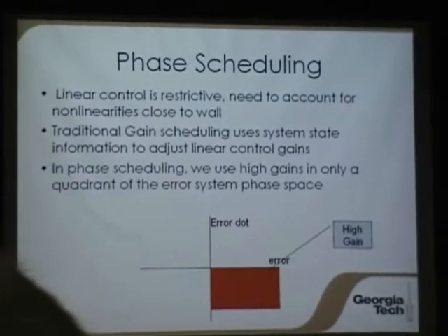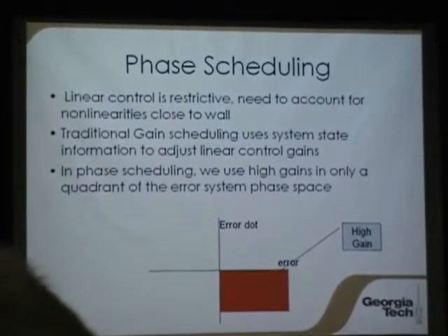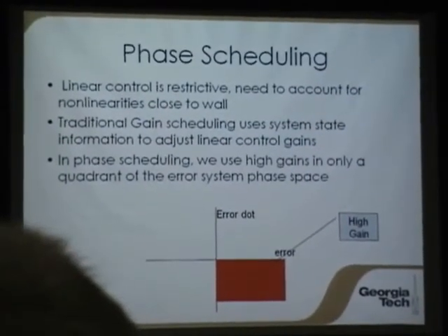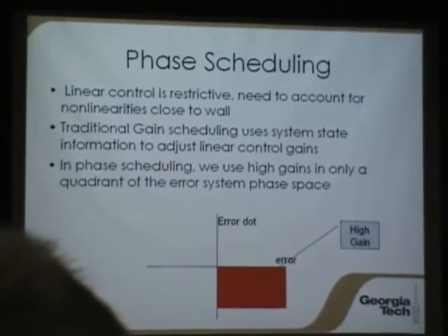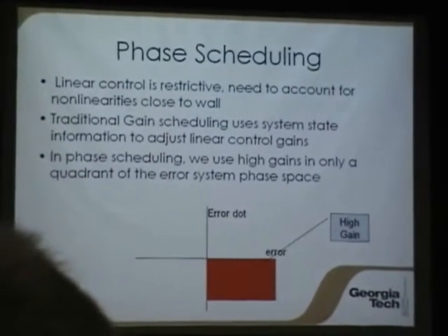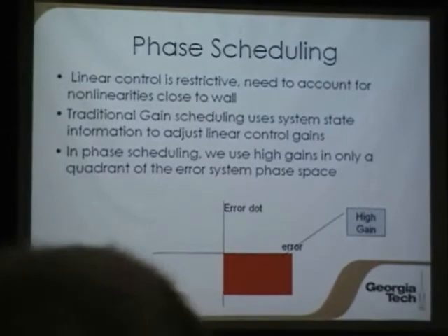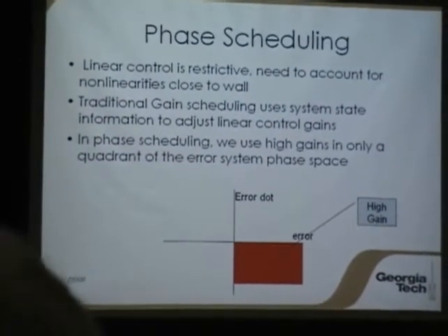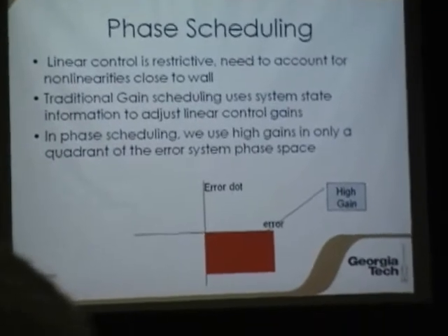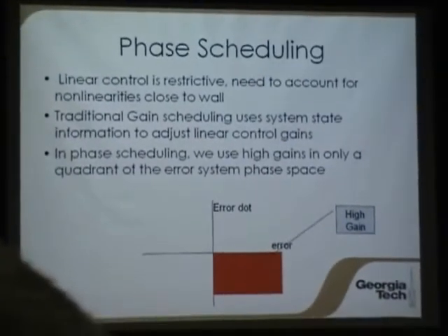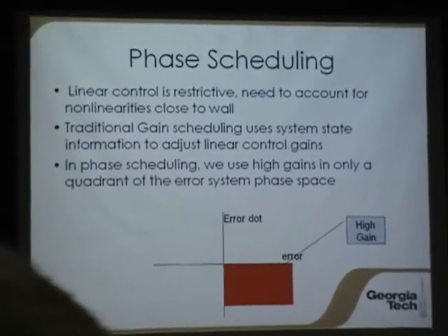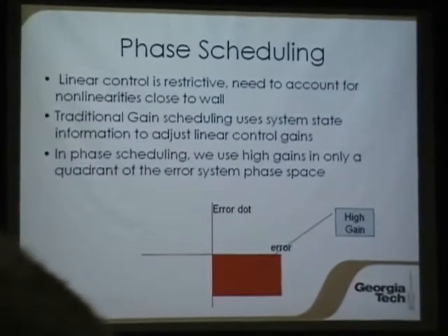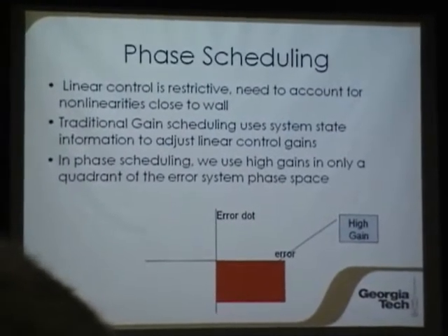Normally, a very standard way of doing this is using gain scheduling or adaptive control. But adaptive control is a little bit hard in this case because this would be what is called an output adaptive control, because you don't have full state measurement. So it's an output based adaptive control. You have to pretty much guess what your states are. And that's not the best thing to do.